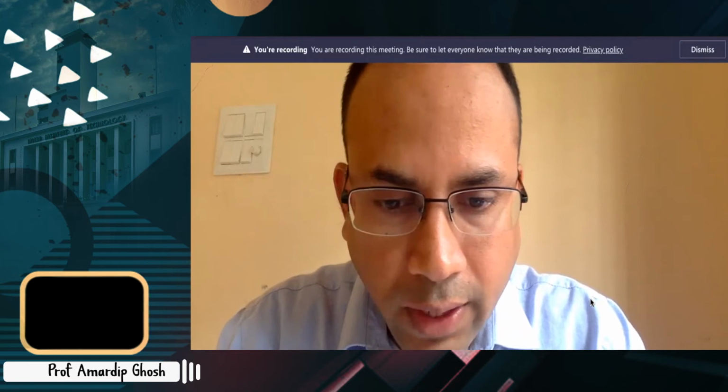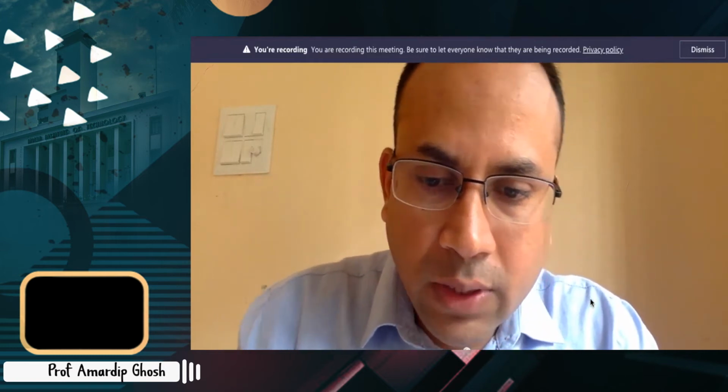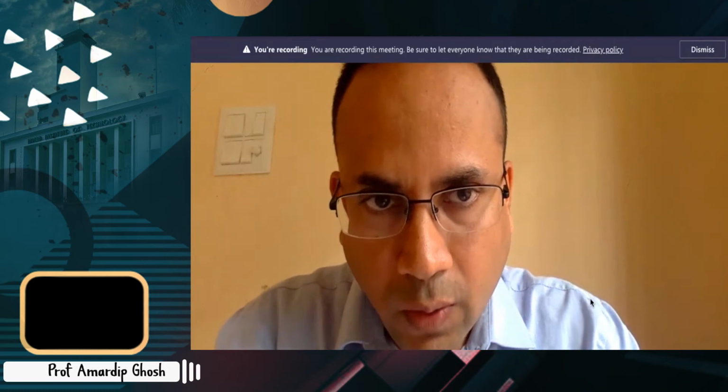Welcome to this another session of our discussion on aerodynamics. In today's class, we will continue with our discussion on lift-induced drag. As you remember, we have talked about various sources of drag on our aircraft, primarily the aircraft wing. So we have talked about skin friction drag. We have talked about pressure drag due to flow separation. At high subsonic speeds and of course supersonic speeds, we have talked about wave drag. And right now, in the previous lecture and in today's lecture, we will be discussing lift-induced drag.